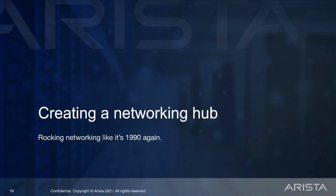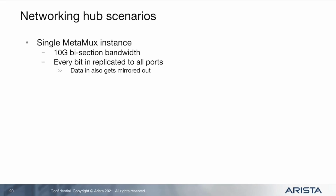One of the weird and wonderful things that we have been seeing built using this hardware is the creation of high-speed networking hubs. This is quite a niche use, but we thought it would be fun to revisit 1990 with modern day speeds. There are several ways to create a networking hub, one being larger size, while the other is being more flexible. The first scenario we want to explore is using a single Metamux instance. Because every bit is being replicated to all of the ports, the maximum bisection bandwidth of this mux is 10 gigabits per second.